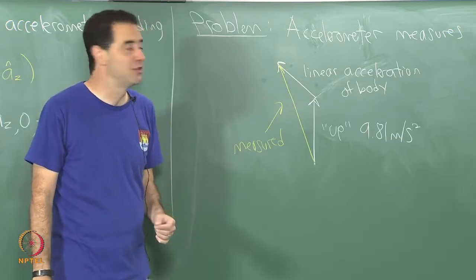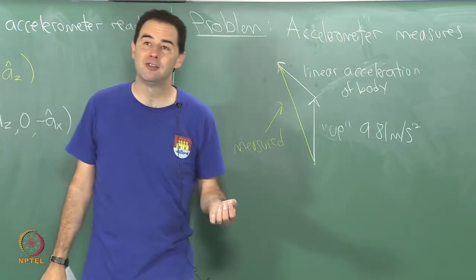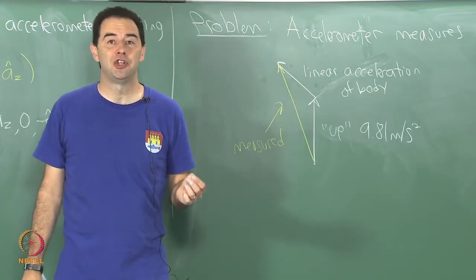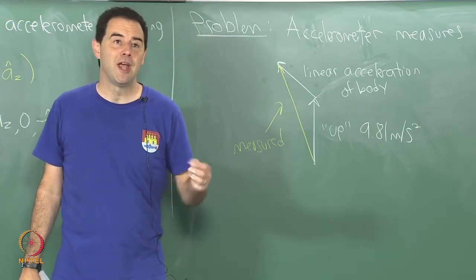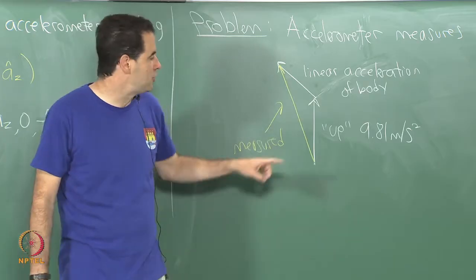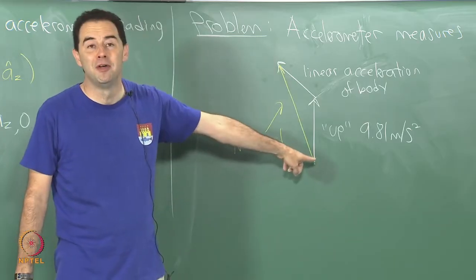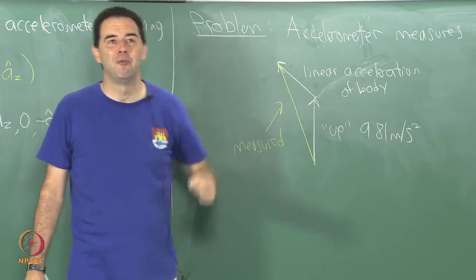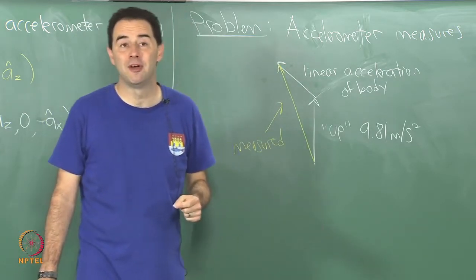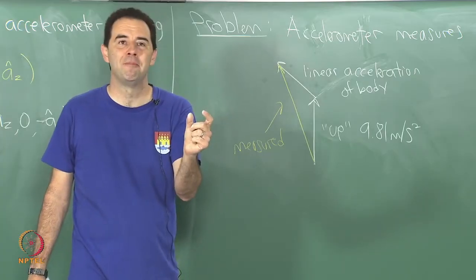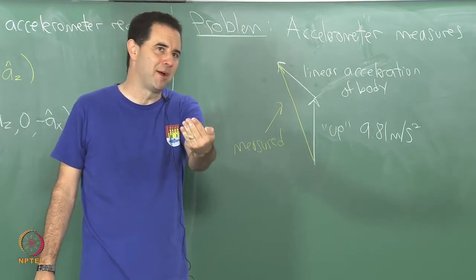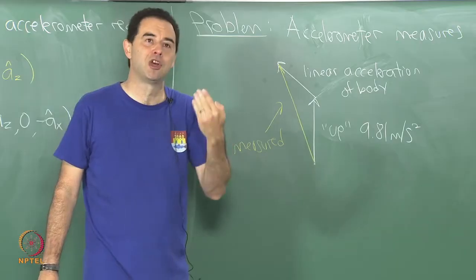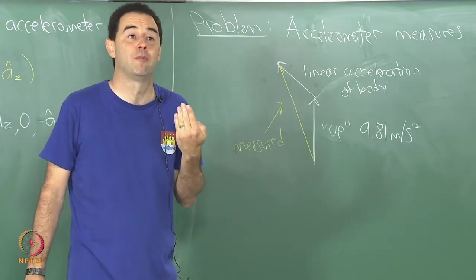It's reasonable in many cases, but you have additional information because you also have access to the gyro, which is giving you the angular velocity. So if you all of a sudden get an estimate of up that's very different from what you previously believed up was in the global frame, and it happened in a short amount of time, you can very easily compare that with the gyro history, because you're integrating the gyro forward and the drift rate is not too bad in a short amount of time.